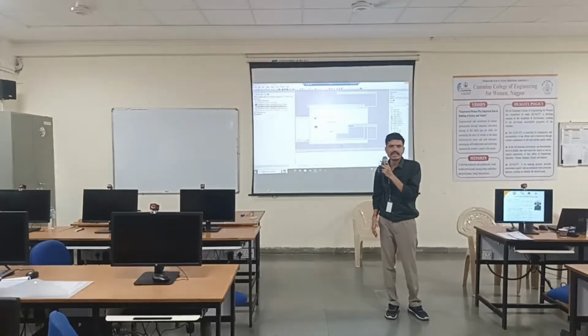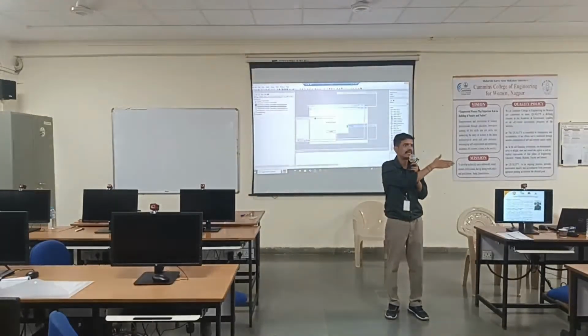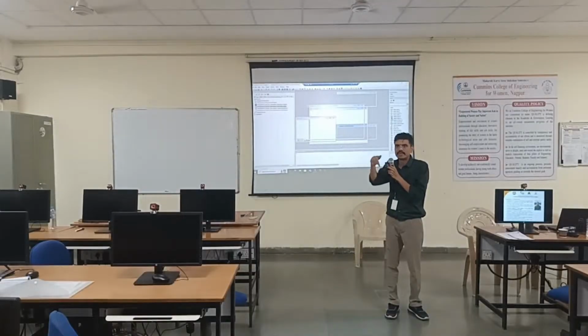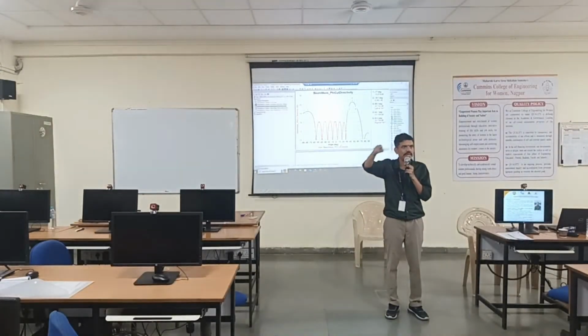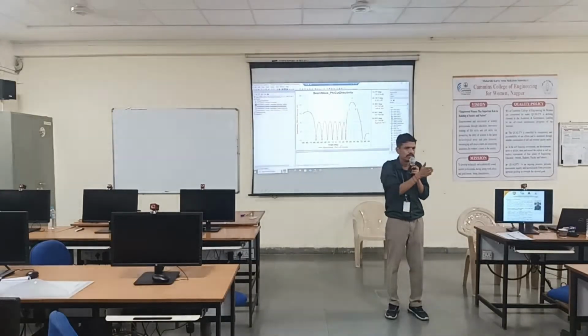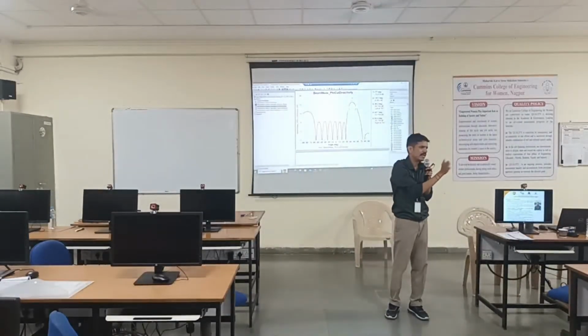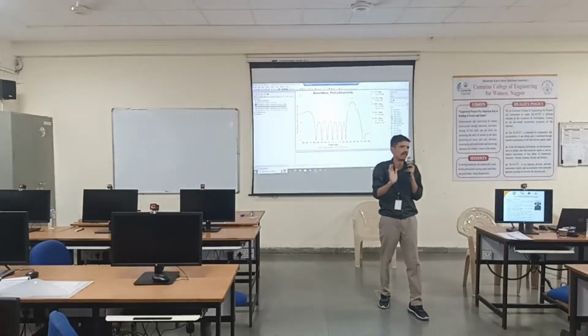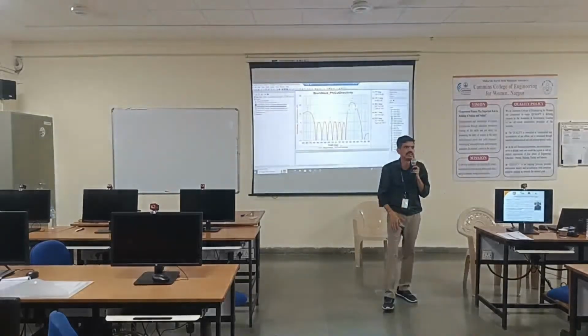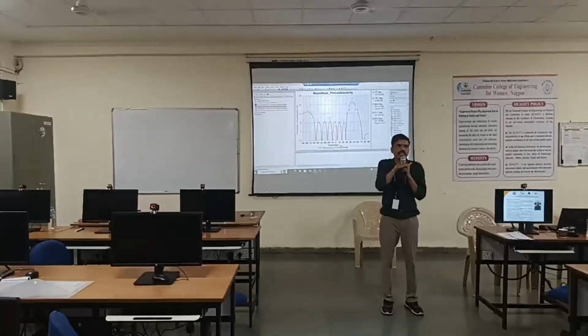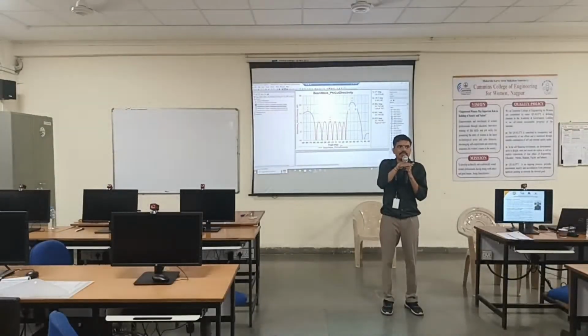Antenna, I mean mechanically the antenna will not move; its radiation pattern will move. It has a main beam, side lobes and a back lobe. So I will show you the radiation pattern which I can move from 0 to plus or minus any angle. Let us say we are doing ±45 degrees. You can ask me why 45 only. So there is justification. Similarly, I will show you in vertical that our pre-tilt is 60 degrees.